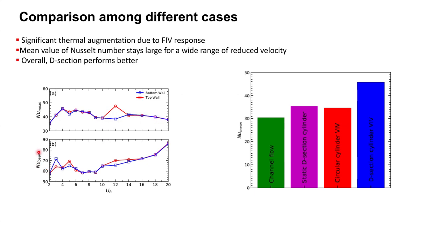Okay. And this is a plot of Nusselt peak. Peak is the peak value which we get in a cycle. So it can go to very large values, but what really matters is the mean value. And so we can actually argue what kind of reduced velocity you will require to improve the heat transfer so that your efficiency can improve. Yesterday, we discussed the pumping efficiency and efficiency of the heat transfer augmentation. All right. So moving on, I'll now discuss more characteristics of galloping and flow induced vibration of the cylinder.